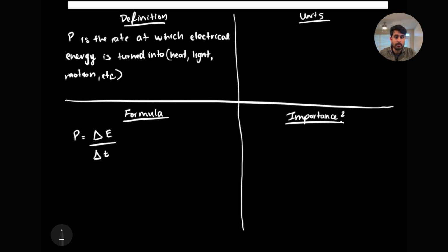Of course, we'll be looking at power from an electrical standpoint here, and there's a couple different ways we can define power when we look at circuits. There are three fundamental ways that we look at power and how we calculate power in any circuit. The three main formulas, and we always use P for our power equation, are P equals V multiplied by I. Power can also be equal to I squared multiplied by R. And power finally can also be equal to V squared over R.